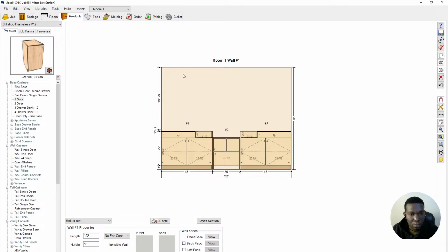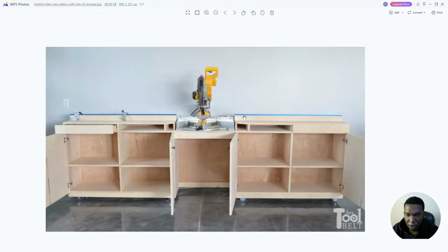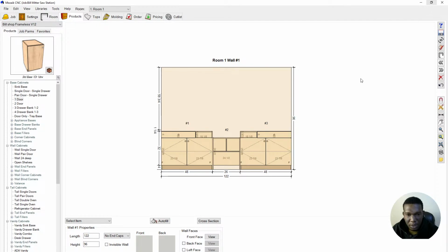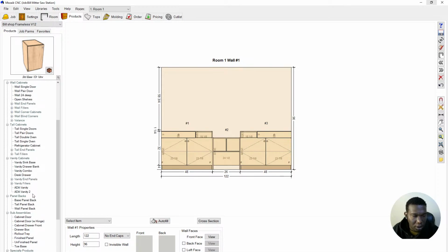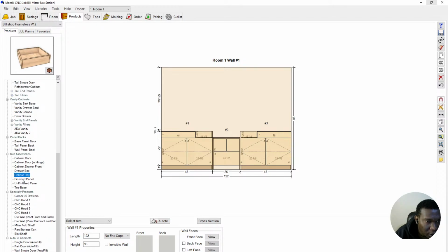But if for some reason you did want to cut this piece here where you're attaching your stoppers, we can just go to floor plan, let's go to elevation, then take something like some panel, any panel you can get which is in shape.